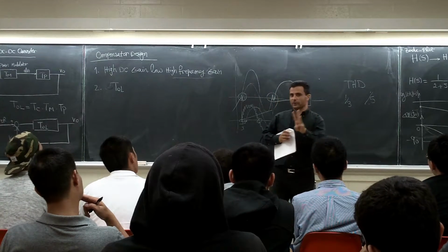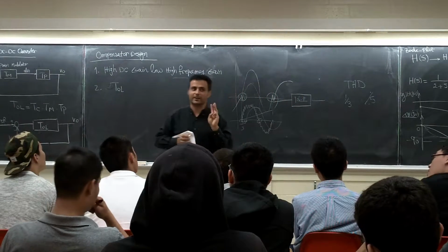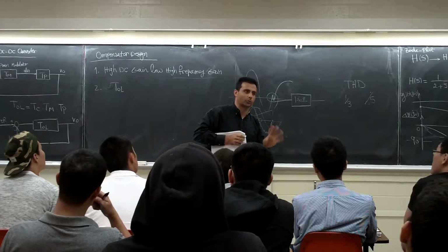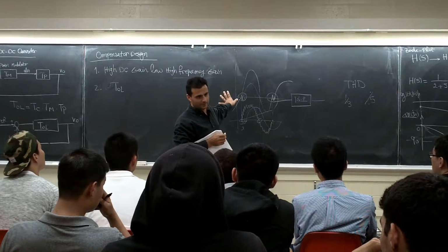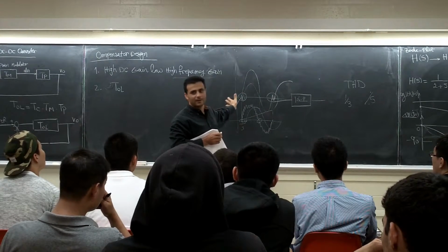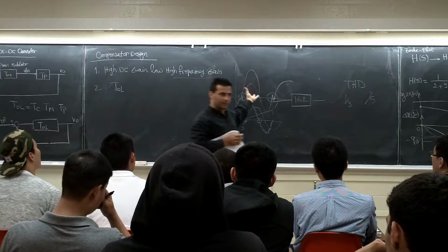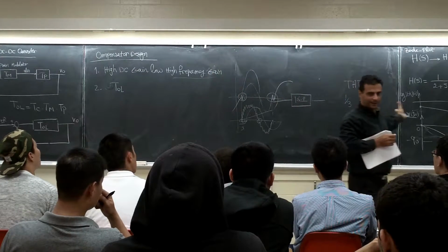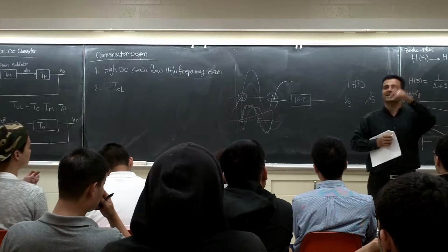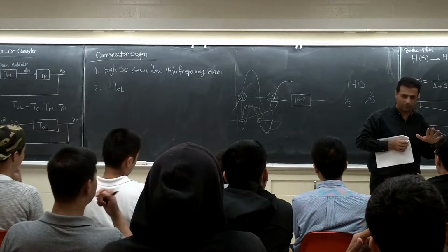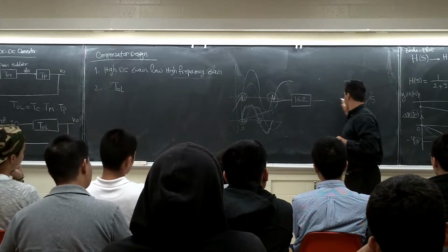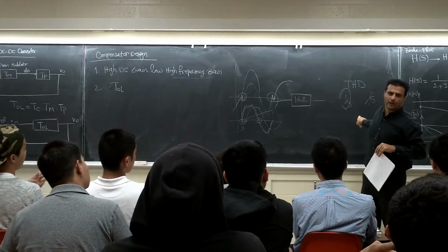Now, the third harmonic and the fifth harmonic have a limitation. Even harmonics, all those things are going to be there. Right now we have a problem with the high-frequency harmonics. We have some around maybe 100,000 hertz. You see here, they are more than what is allowed. The overall THD is less than 5%, so we are good. We are 4.5% for this one, for 1/3. For the full rating, I think we are like 3.2%.